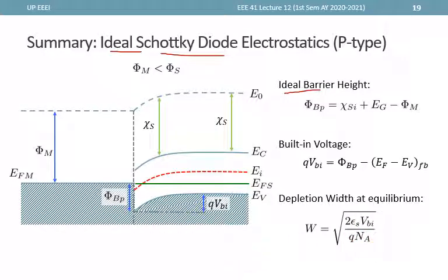And again, as a last note, the energy band diagram for an ohmic MS contact that is p-type should look like this one. Okay, so we have a p-type semiconductor, but the barrier is non-rectifying.